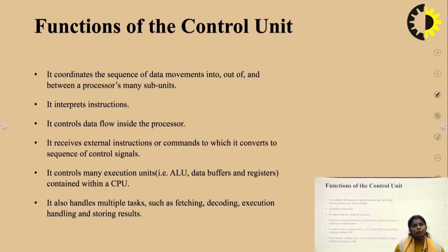When the control unit is designed with sequential or combinational circuits like a decoder, encoder, multiplexer, that is, with all the control hardware, then it is called a hardwired control unit.